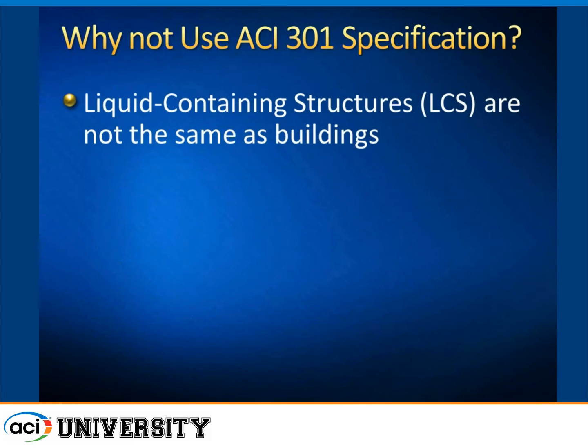And this may be obvious to many of you, but there's a lot of people that do design of buildings that may not really think about it. Liquid containing structures aren't the same as buildings. I've been involved with tanks that have been 70, 75 feet deep. If you think about just a 30-foot wall height full of water, the load, the live load from that water on the floor at the lowest level is about 2,000 pounds per square foot. Those are loads that I don't think you really ever see in a building structure. So we have higher loads.